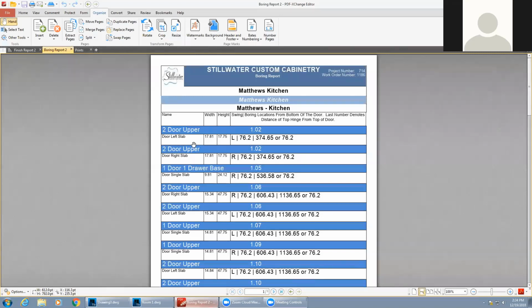A lot of commercial shops, which is obviously where Microvellum was developed, inside of the commercial cabinet industry, I'd say the vast majority, because they're using pre-finished materials and slab doors, just have the CNC machine cut their hinges. So you drill a couple holes and bore the big pocket for the hinge cut, and you're done.